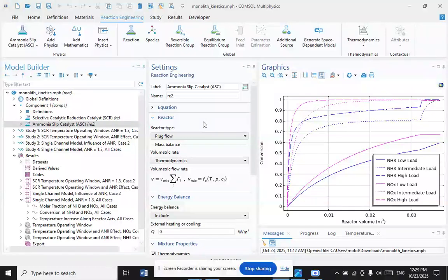Diesel engines produce a variety of particles during the combustion of the fuel-air mix due to incomplete combustion. The composition of the particles varies widely depending upon engine type, age, and the emissions specification that the engine was designed to meet. Two-stroke diesel engines produce more particulate per unit of power than do four-stroke diesel engines, as they burn the fuel-air mix less completely.